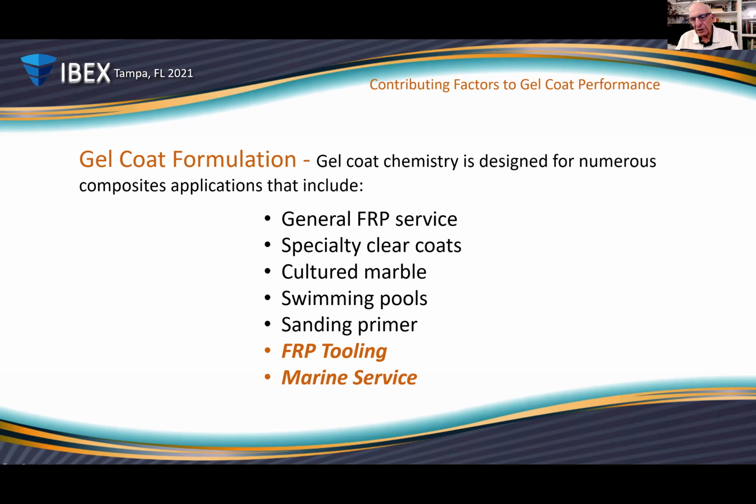So the fine line that the gel coat manufacturers are walking is, how do we make the most highly glossy gel coat we can, and yet it still has the toughness? Technically, that's modulus of elasticity. It has that toughness that it's going to not crack and hold up for the particular service.